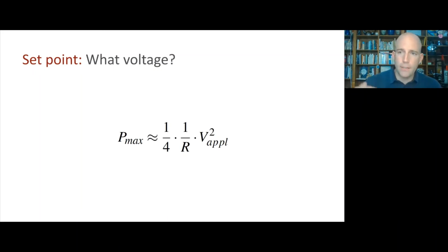And power is work over time. So if our time gets smaller, our power gets higher. So we're really trying to maximize power output. And power is proportional to voltage squared. So we want to choose the maximum voltage that we can. In this case, it was 6 volts. And then later we'll want to check things like, will my motor overheat if I do that?